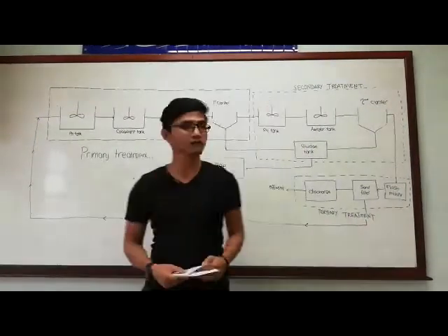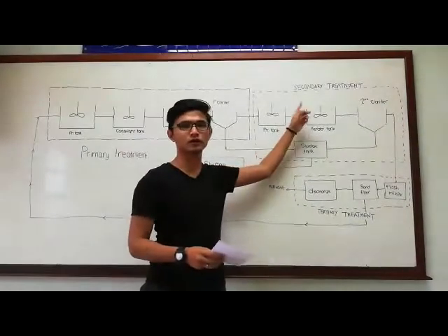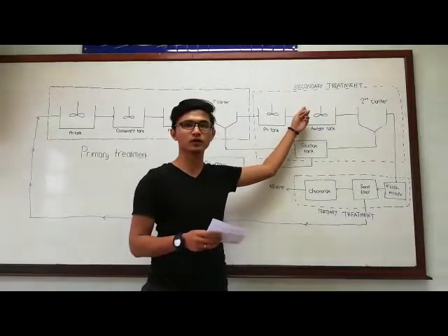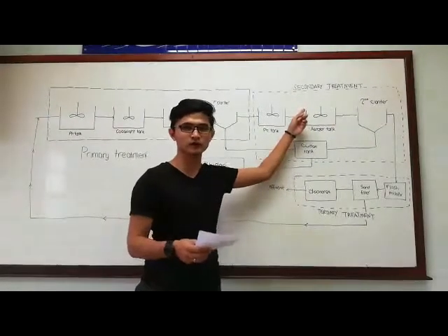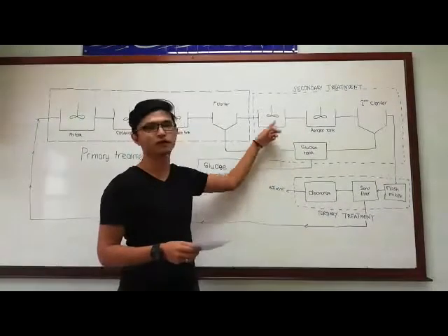So after the primary treatment, we will move to the secondary treatment, which will focus on BOD and COD and the microorganisms. Okay, first of all, the first step for secondary treatment is the pH tank.